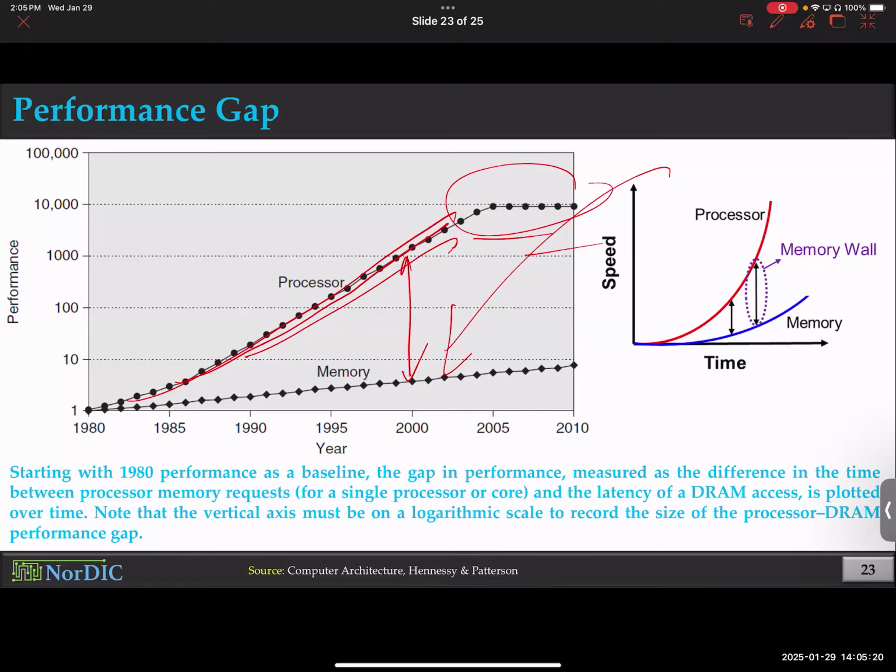And you cannot even use the memories to the full extent of their ability, because if you read them too frequently, there is a chance of accidental flipping. Am I making sense? I tend to use a simple example there. Imagine you are using a ferroelectric memory. Ferroelectric material has domains, and the more you read, you create some disturbance, and the domains gradually relax. By reading it too many times, you essentially risk destroying the stored data. So you have to read, let it relax a little bit, and then read again, let it relax a little bit, okay?